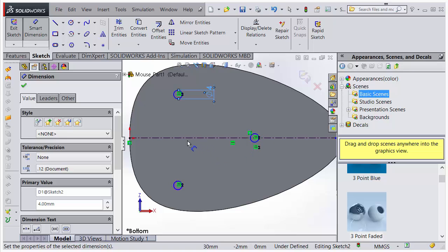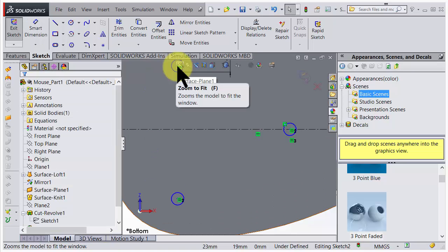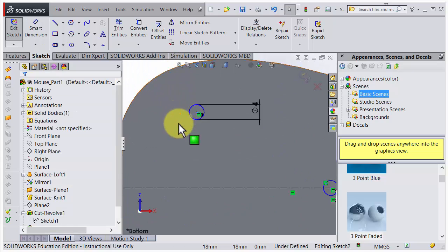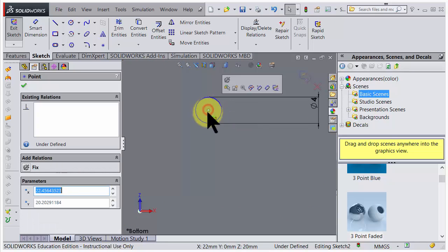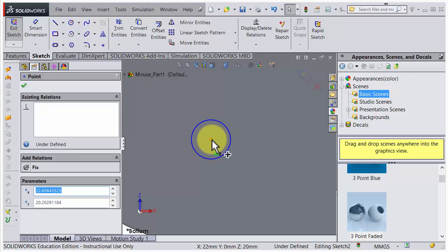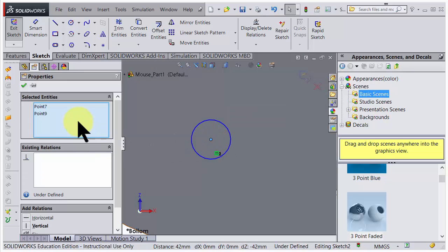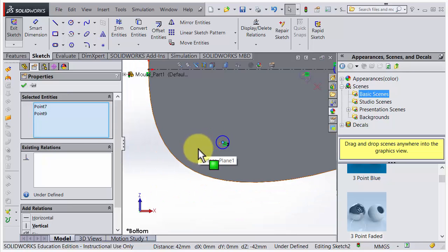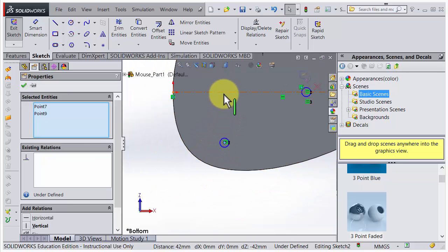One important thing though that I almost forgot is this should of course be symmetrical. So to make this symmetrical, I zoom in and pick that one. I shift click that one. You can see how the points are added there, and then I shift click a center line. That should give us symmetric as a possibility here, as a constraint.